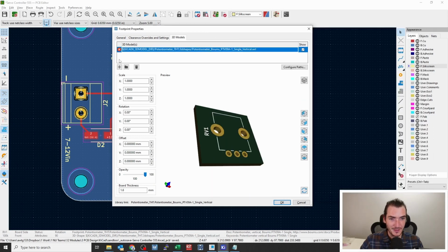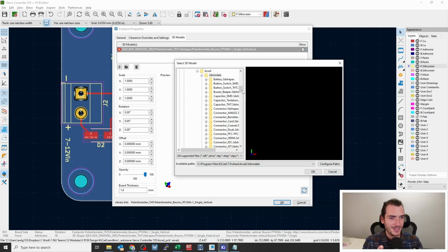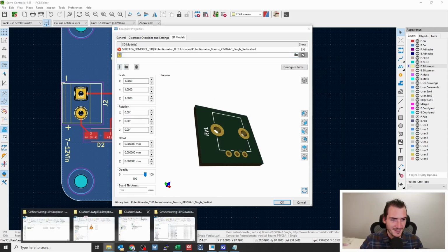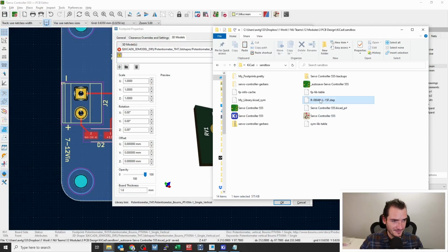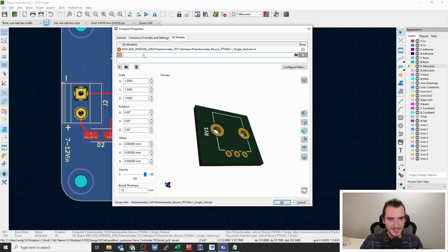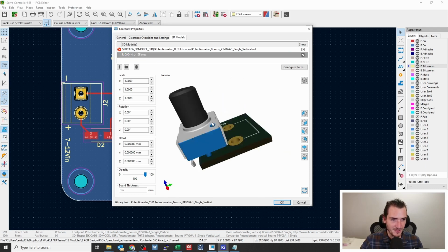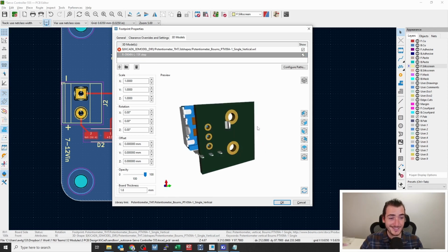So in the 3D model view, I can open from a directory. And this tree is different in KiCAD for some reason. It can be a little bit overwhelming, but I'm just going to create a new entry and then take my file name and just paste that in, because it will look under the project directory by default. I strike tab and there's my model, and you can see things are a little bit scuffed, and this is pretty common.